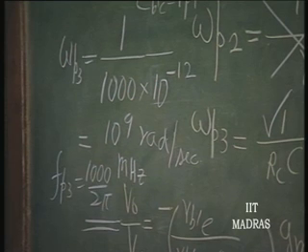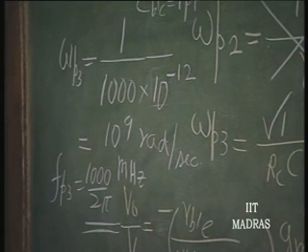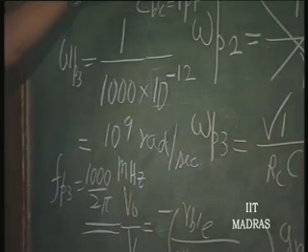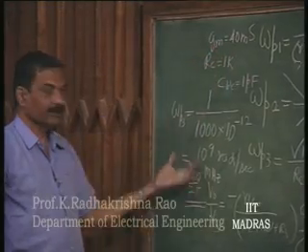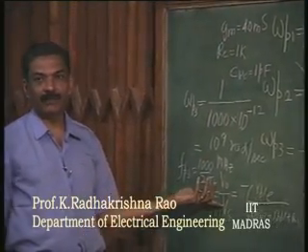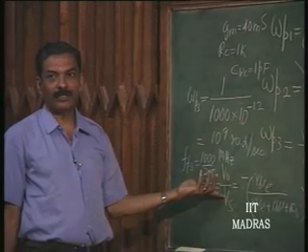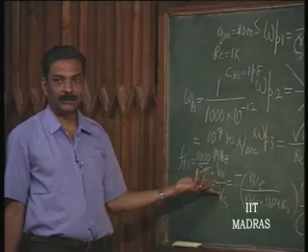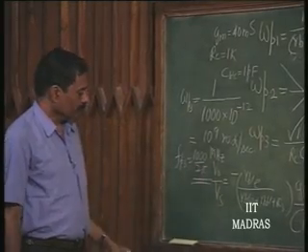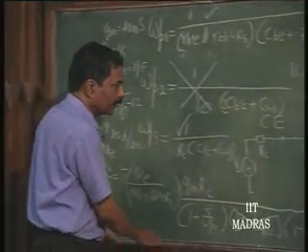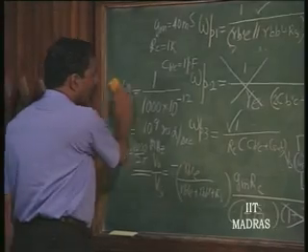Which is a very high frequency. So, even if you consider this as few picofarads, this is definitely usable for a wideband amplifier, that is a video amplifier, which is of the order of few megahertz. So, this kind of structure is pretty common.